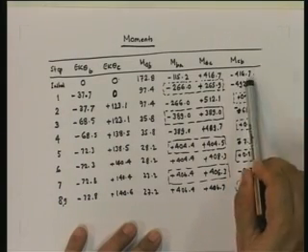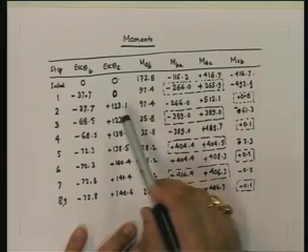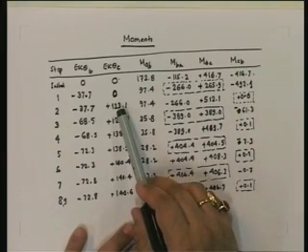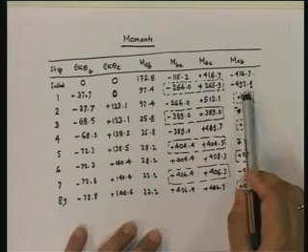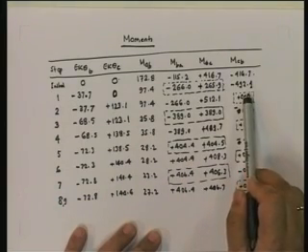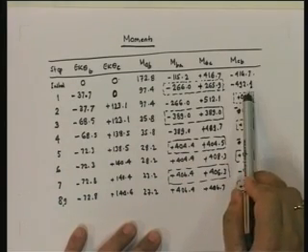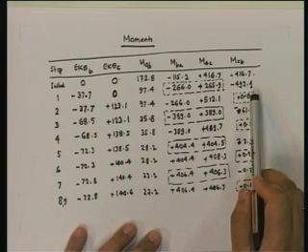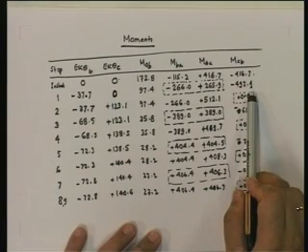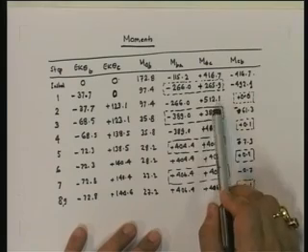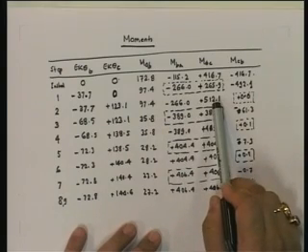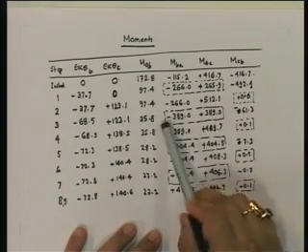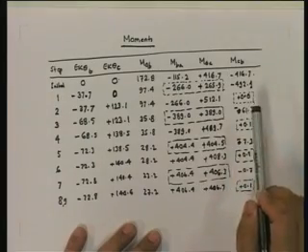When you release this, you get Ek theta C as this, then immediately you have this going to 0 because you've released the clamp at C. So the moment at C has to go to 0. But that creates an unbalanced moment here. So now you distribute those moments. When you distribute those moments, it creates an unbalanced moment again here.